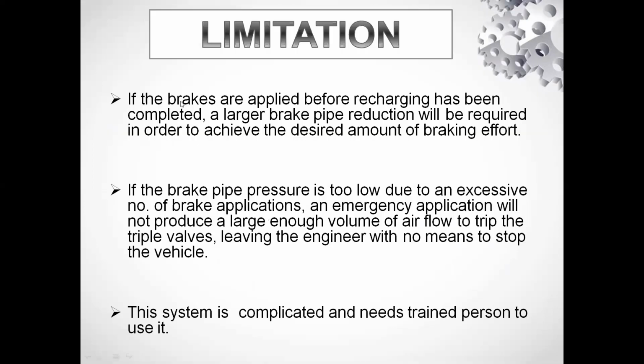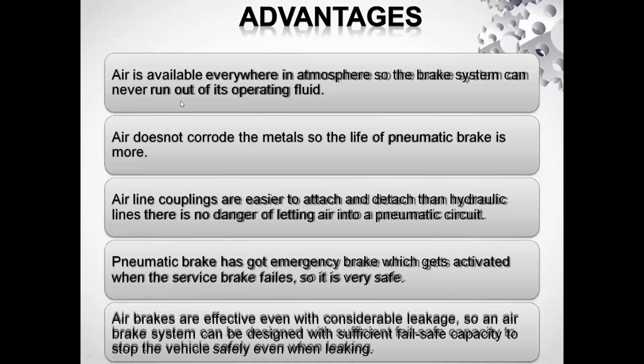What are the advantages? You can see air is available everywhere in the atmosphere, so the brake system can never run out of its operating fuel. So the main advantage is air is available everywhere. Air does not corrode the metals, so the life of pneumatic brakes is more.